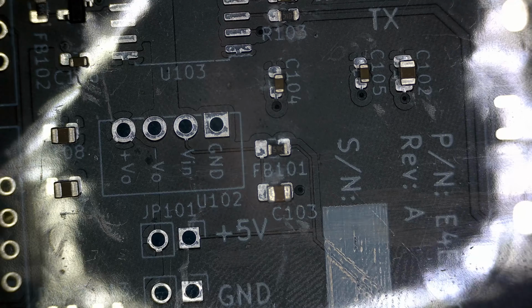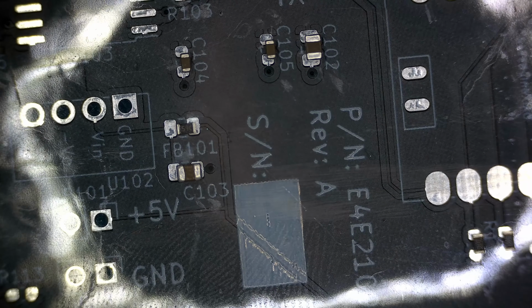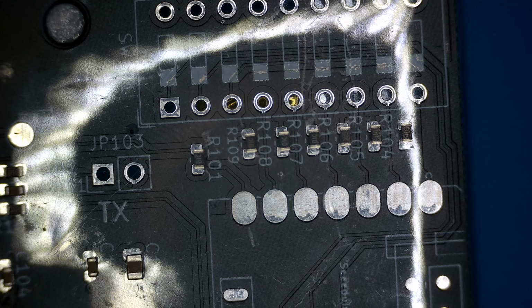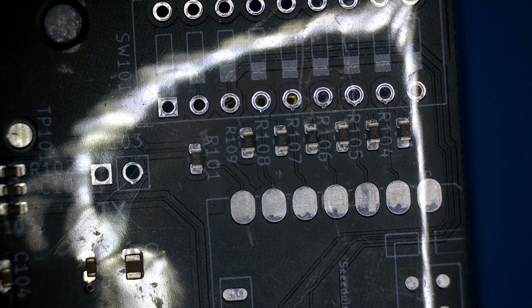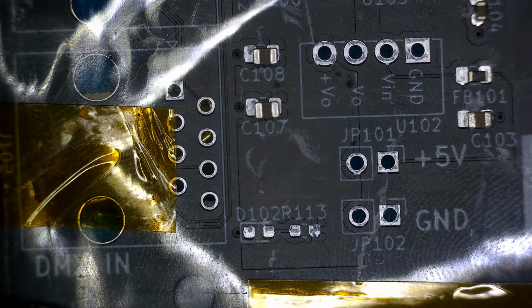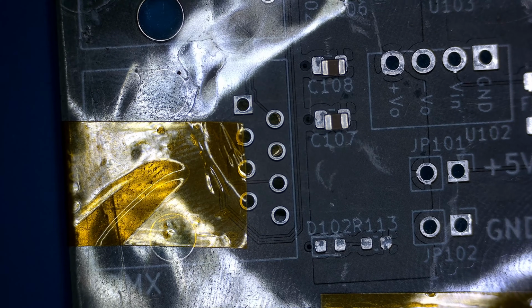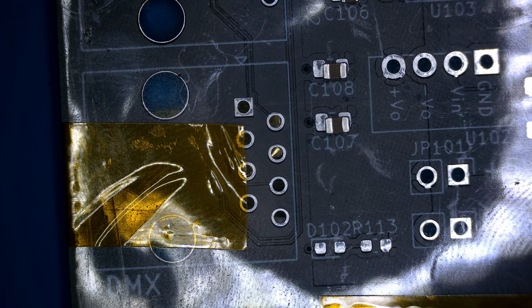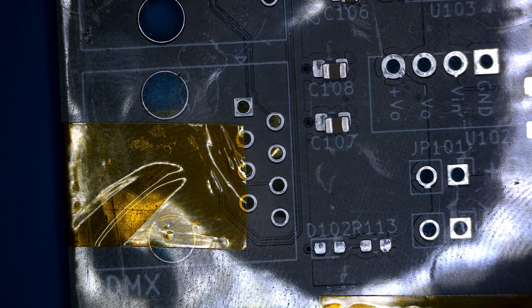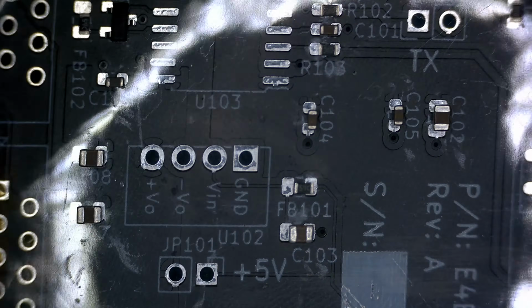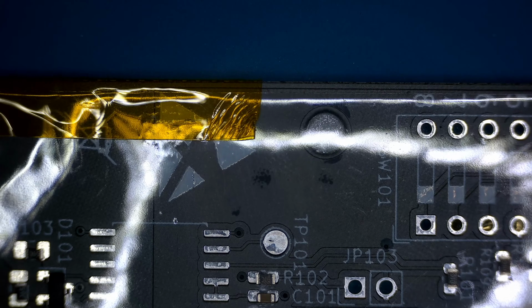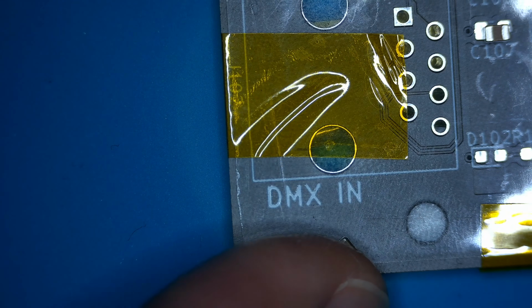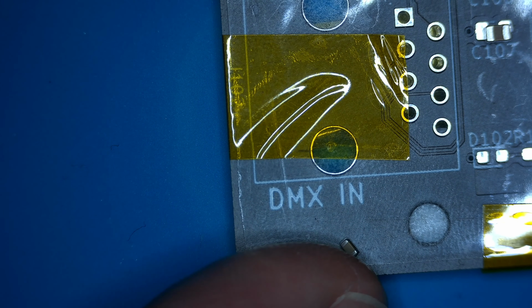And unfortunately, because our fiducials were so bad, we have two different kinds of error. You can see that pad on the far right is shifted a little bit up and a little to the right. And then as we go to the other side of the board, you can see these are shifted a little bit to the south and even more to the right. So that means not only is there an absolute error, there's also a relative error, because when this came in to home and it tried to find the center of that fiducial, it was a little bit wrong on one or both of those exact centers.